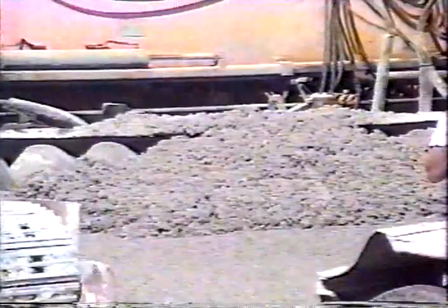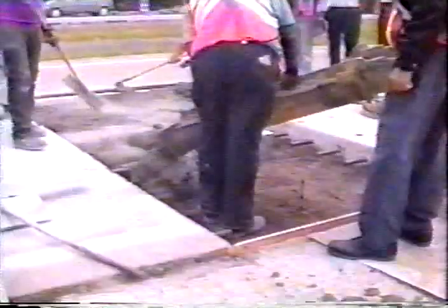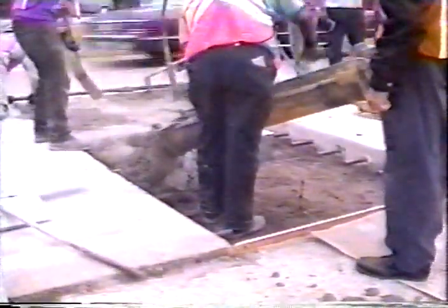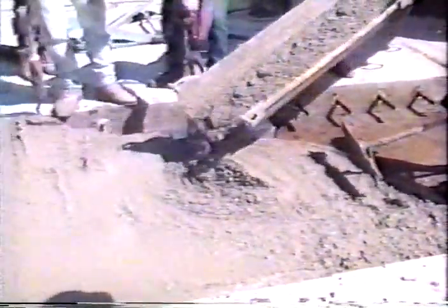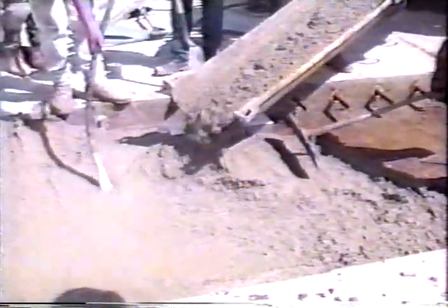Concrete may be under-consolidated in areas away from the vibrators, where the vibration energy has diminished. Consolidation problems may also occur near slab bottoms, between slip-form vibrator paths, around reinforcing steel, and around dowel bars. Quick corrective action can be taken while the concrete is still plastic, such as revibration or resetting the hydraulic vibrator frequency, magnitude, and depth.